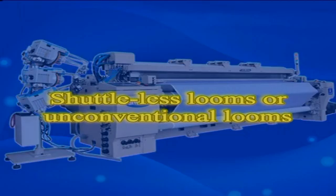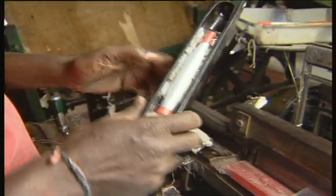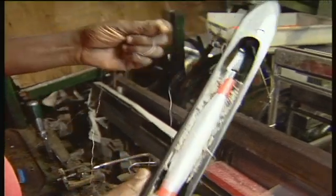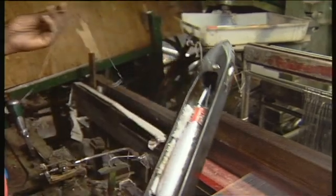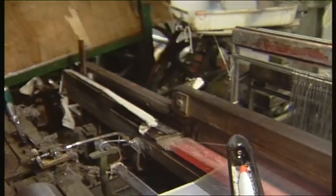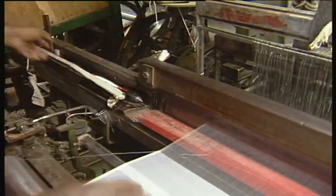Coming to the shuttle-less looms or unconventional looms. In the non-automatic and automatic looms, shuttles are used for inserting the weft yarns. In these shuttle looms, preparation of weft yarn and the weft insertion mechanism itself limit the loom production and fabric quality. They are also prone to mechanical problems in propelling the shuttle. Hence, loom manufacturers have developed looms with various innovative and alternative means of weft insertion.